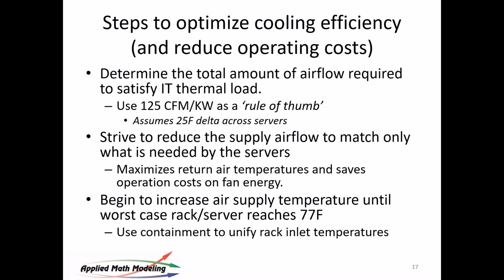And on air supply temp as well, there is a point where if you get too high, the servers will start to kick into overdrive on their thermal control system and ramp the fans up, and then you're losing. That number that is often referenced is 77F. I apologize to my international community who's going, what is F? But we're in America and we use Fahrenheit. Right around 77, the thermal systems in the server start to ramp, and you begin to lose your advantage.